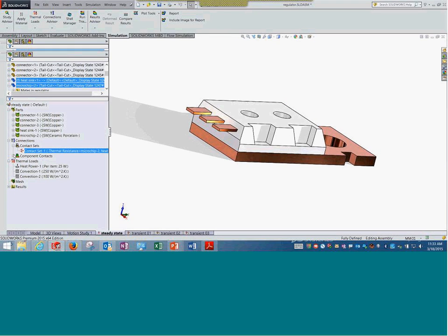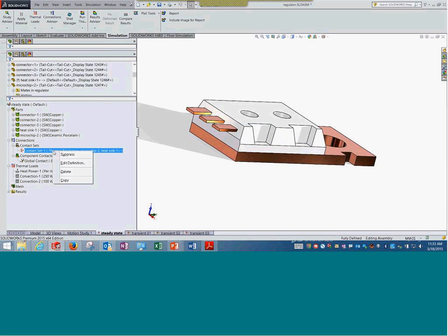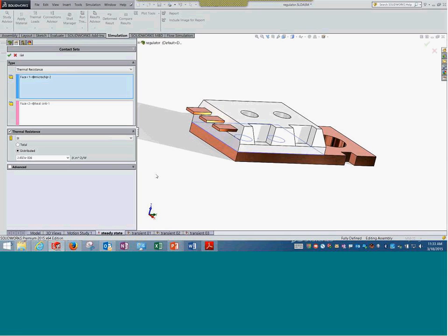The contact conditions would be a little bit different. If we set the default contact condition to bonded, we are saying that there is no resistance to heat flow between two parts. Otherwise, typically there will be some amount of resistance because of surface roughness, because of the glue that has been used, or whatever comes between these two parts. Simulating that is obviously difficult, but it can be simulated mathematically using the resistance option given in the software. So it could be insulated, wherein no heat transfer happens. It could be bonded, wherein 100% heat transfer happens. And third, it could be thermal resistance, also called no penetration contact, wherein heat is moving but with an amount of resistance, and that amount of resistance is given as a value over here.